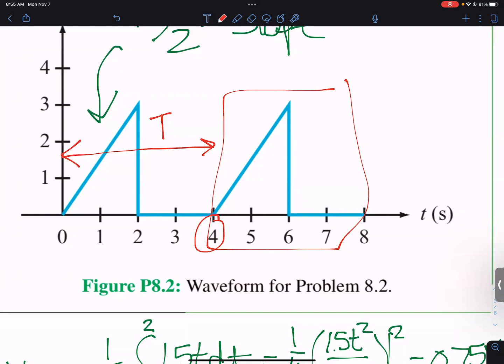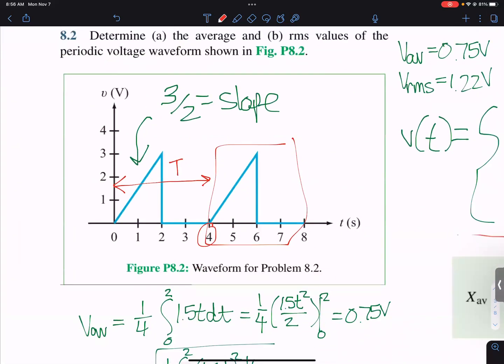Oh, wait, no. Okay, so it's just however long that time period is. This can be skewed when you look at these on an oscilloscope. You're not going to have an exact 0 time frame. On an oscilloscope, you have to ask, where is my period here? You define where 0 is, and then you look at where it will repeat itself. In all of these nice graphs, you get 0 told to you, but on an oscilloscope, you have to define where that 0 point is. Okay.